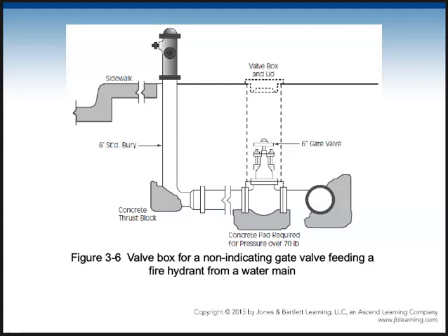All of this is a typical assembly for just one fire hydrant. But what they're going to do is bury this valve, but they want you to have access to the valve, so they'll put that in a pipe type housing, but it can be 6, 8 feet underground. So we need that big long T key valve.